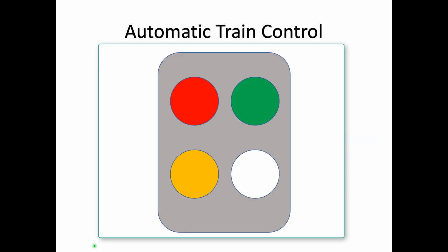But in any case, all the way from Chicago to Omaha, the only wayside signals on the Chicago Northwestern were at control points. It relies on a continuous coded signal sent through the rails, similar to cab signals. In a locomotive cab, there was a box with two lights on it that signaled either clear or restricting. With the green clear light lit, you could proceed at maximum authorized speed.